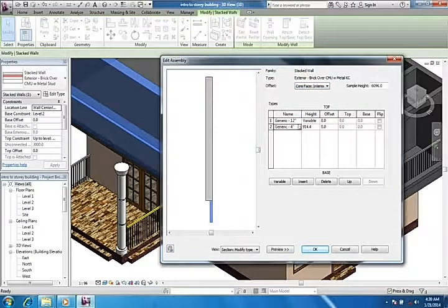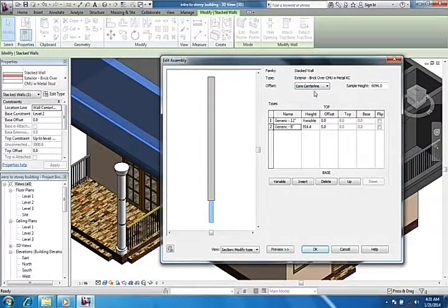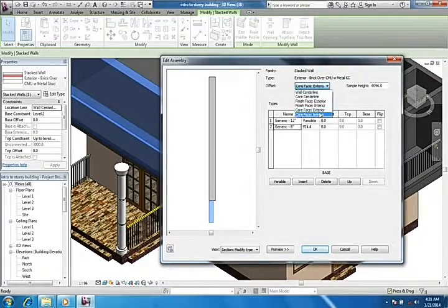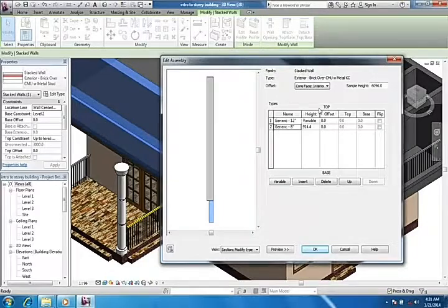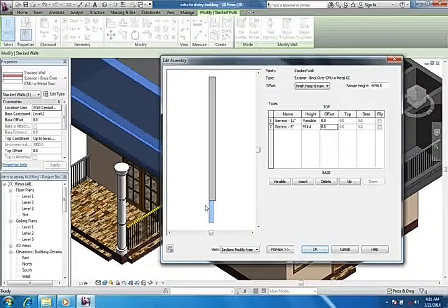Now usually I don't like the both of them having the same thickness, so I'm going to select a lesser thickness, say generic 8 inches. Now work on this side. I think this is, let me not select that. Let me look for something else. I want it to shoot out to the left a little, or I can change the offset to say 50. That's the number 2. Once I click, I think it's okay like this.